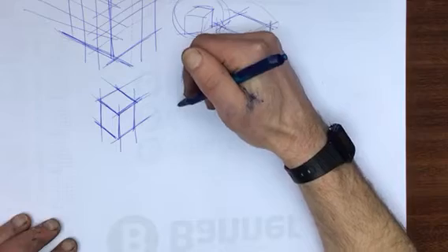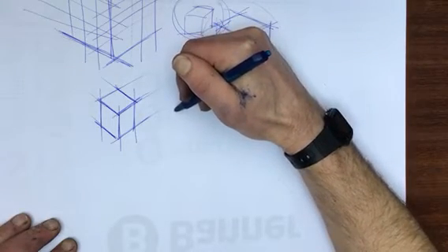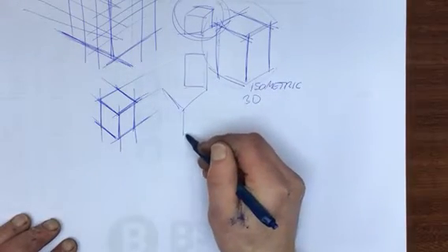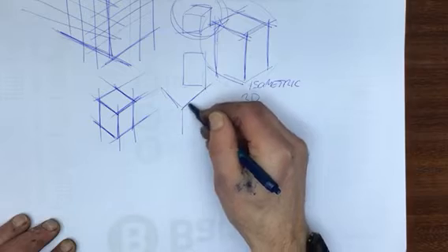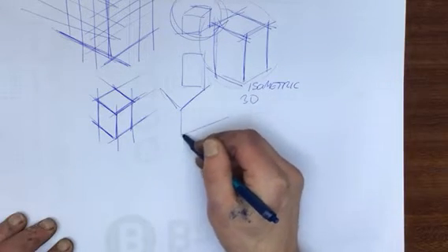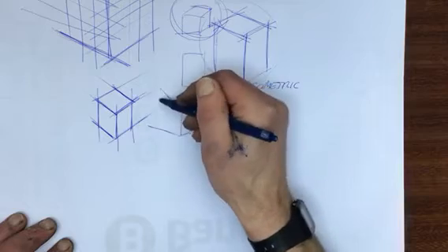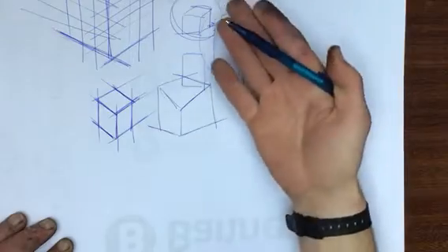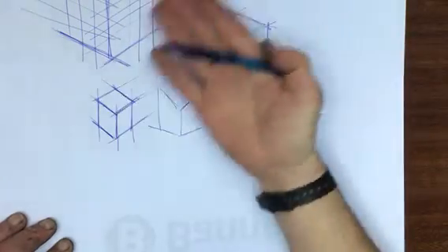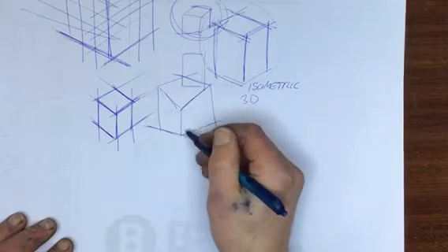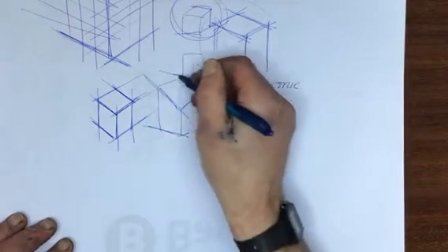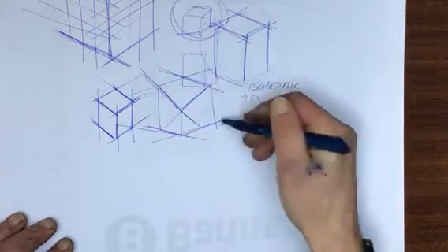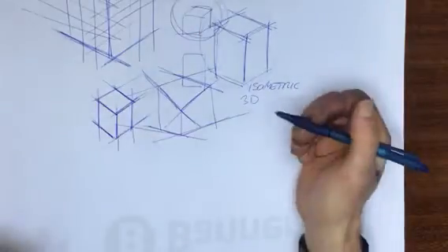Now sometimes when I'm drawing with lads, they start right like this, start with a Y shape, and then rather than continue in the same direction like this, the lines go off like this, and we end up with it's like a box with a corner cut away from it. And that's because this line and this line are not parallel. We see there's 3 different directions here, and the same here. 1, 2, 3. They're all twisted. This box is a twisted, chopped up box.